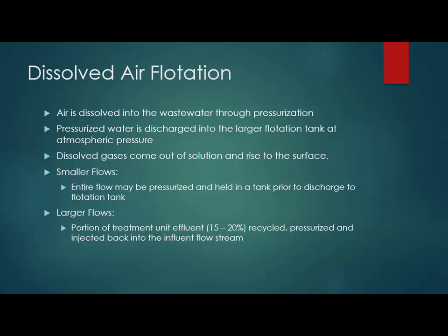So first we'll talk about dissolved air flotation. This is probably the most common flotation process used. In this process, air is dissolved into the wastewater through pressurization. Then as the pressurized water is discharged into the flotation tank, the pressure drops, and the air that has been absorbed into or dissolved into the water comes out of solution and rises to the surface.